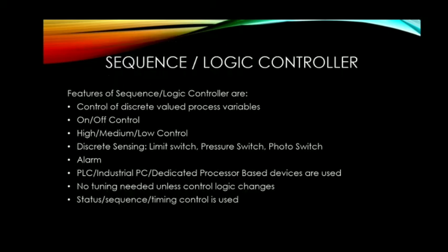Many control applications do not involve analog process variables, that is, the ones which can assume a continuous range of values, but instead variables that are set valued, that is, they only assume values belonging to a finite set. The simplest examples of such variables are binary variables 1 or 0, on or off, open or closed. These control systems operate by turning on and off switches, motors, valves, and other devices in response to operating conditions and as a function of time.